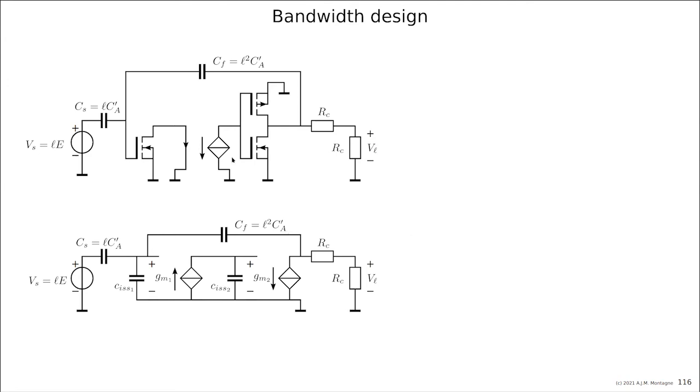Only later on we are going to implement this inverting current amplifier as a current mirror, and then we add another pole, and you don't do that. You have already here your complete model. That's why probably your solution will be easier and better in the performance.